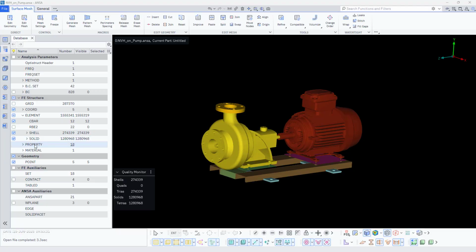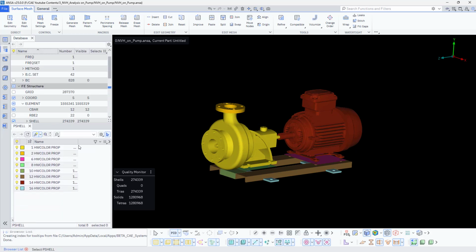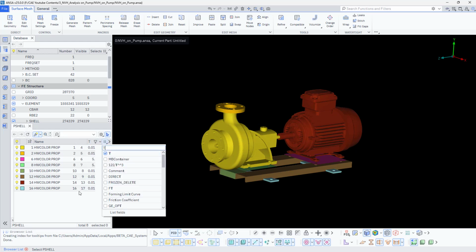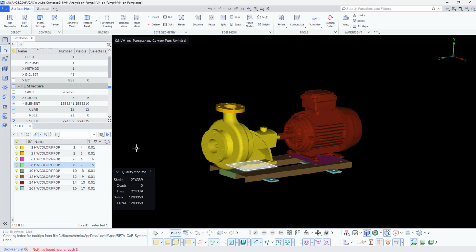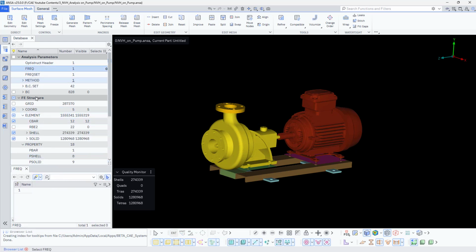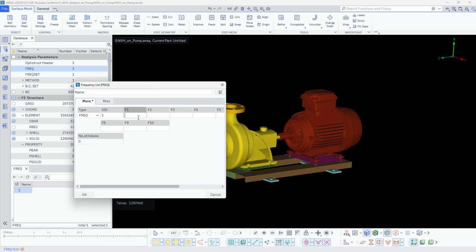Okay, so this is the model, which I said I'm going to refer to, the previous NVH model which I had set up. I'm just looking for the thickness. So this plate has 5 mm thickness, which I had considered earlier. That's fine for me now. Let's go to a frequency card. Here you can see this FREQ1 card. I need the FREQ card where I can enter the frequency values. As we mentioned, 265 hertz and 310 hertz were the critical ones, and I would like to see the excitations, just to check how it is going to behave.